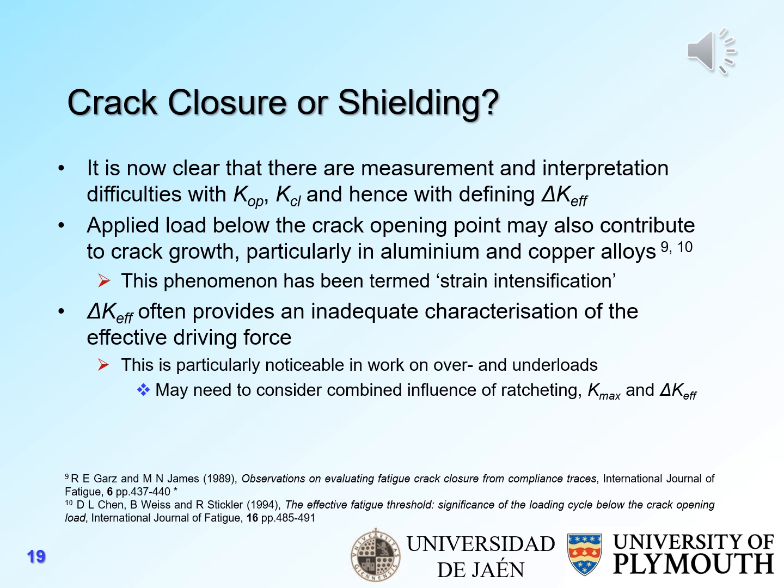And so delta K effective often provides an inadequate characterization of effective driving force, and that's particularly noticeable in work on overloads and underloads. And it's becoming clear from several workers that you may need to consider the combined influence of ratcheting, perhaps of Kmax, and of any delta K effective. And of course you still need to know how to define delta K effective, which is not clear.